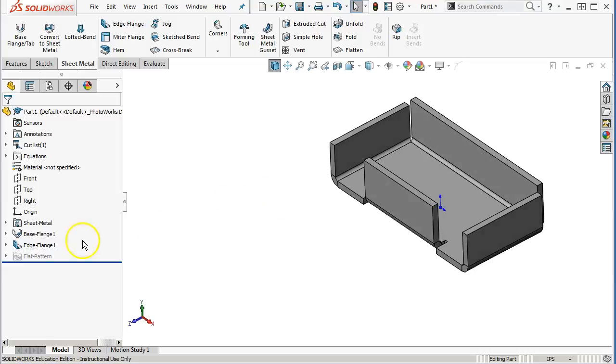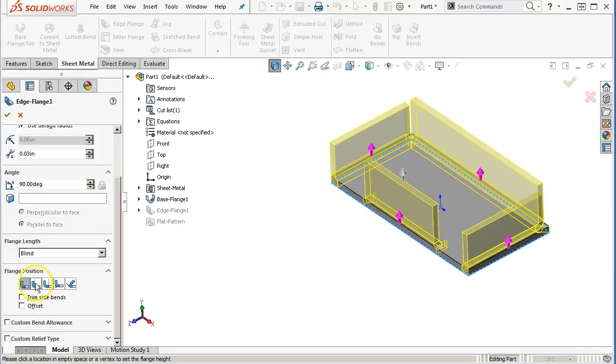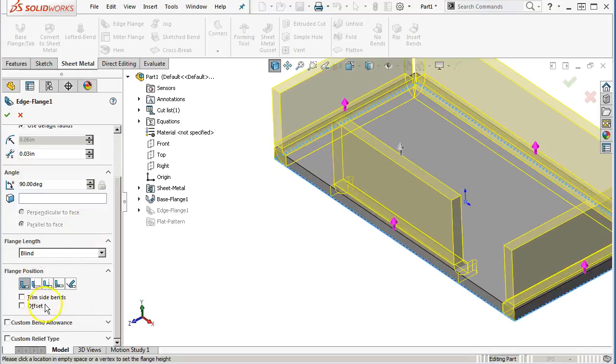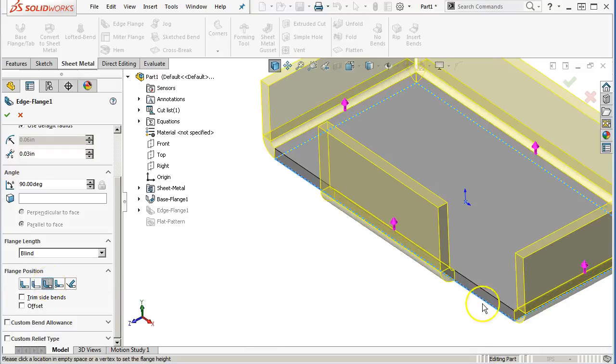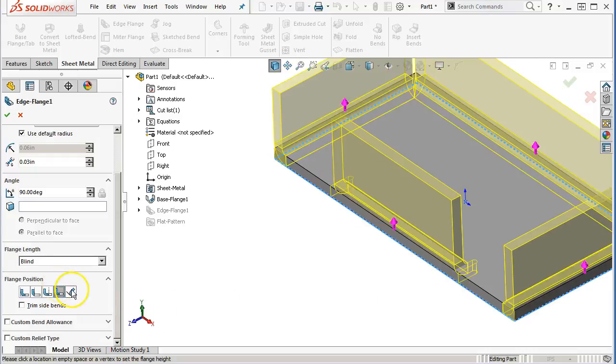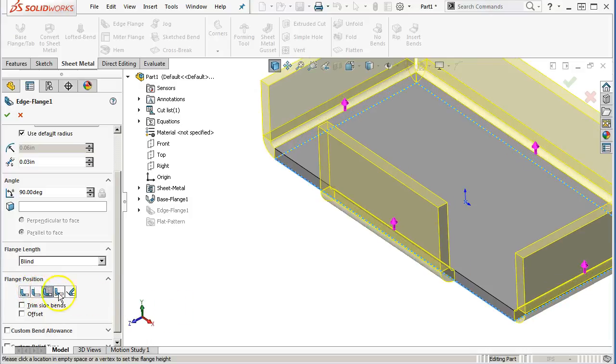All right, so the difference would be then going back one more time, and now that we have the relief, I go to the outside, the relief gets smaller. I go to outside the bend, it goes away entirely. You shouldn't see too much in the way of the tangency. They just kind of jump back. Okay, so where I can get away with it, bend to the outside.